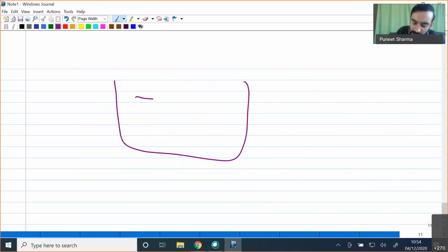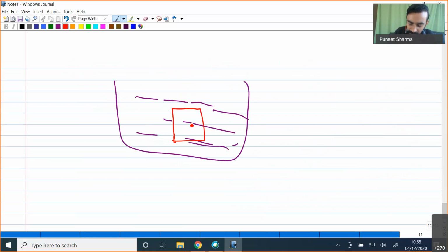Okay, so for an ideal gas temperature measurement device, what we do, for example, if I have a fluid for which I want to measure the temperature, I'll be putting this container inside that particular medium. Obviously, this medium will reach thermal equilibrium with the container, and inside this container we will be connecting a pressure gauge,